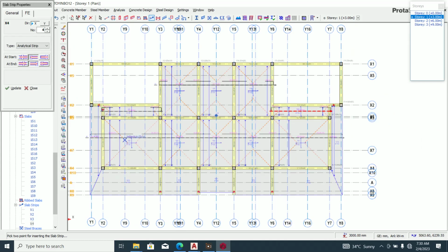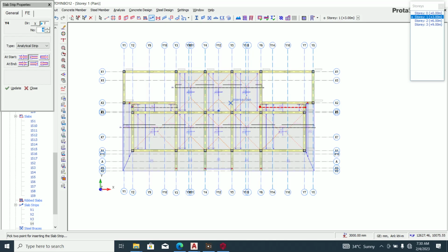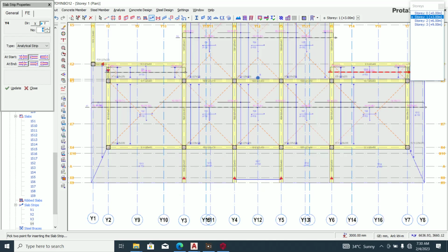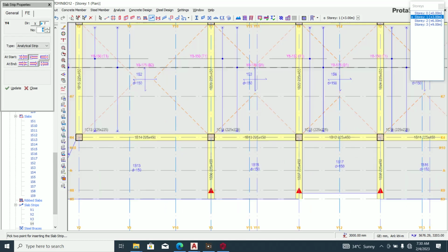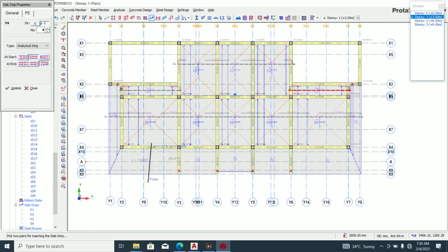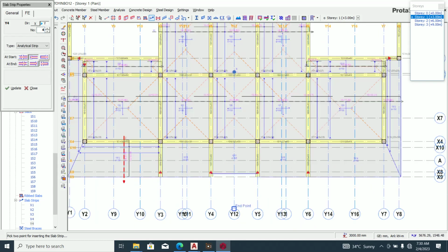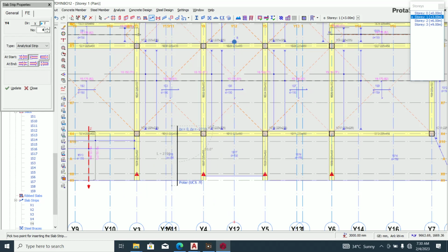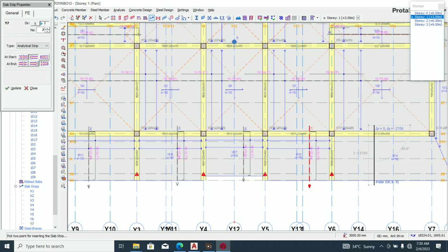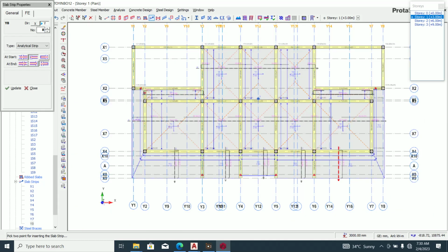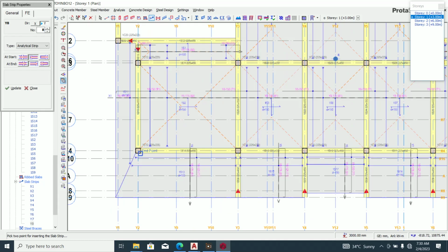So we are done with x axis, we go to y axis. We have from here to here, that's beam to cantilever. Hold on your control button, beam to cantilever, and so on for each. After beam to cantilever, you come to beam to beam.